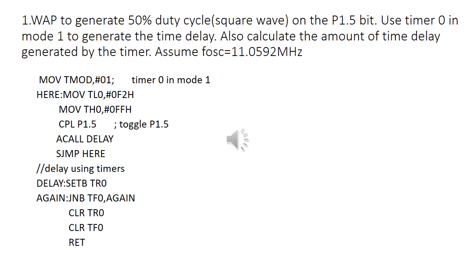Since this problem does not mention the frequency of the square wave, you can consider any value to load into these registers. In this problem, I am going to consider the value FF loaded in TH0, and in TL0, I loaded the value F2.